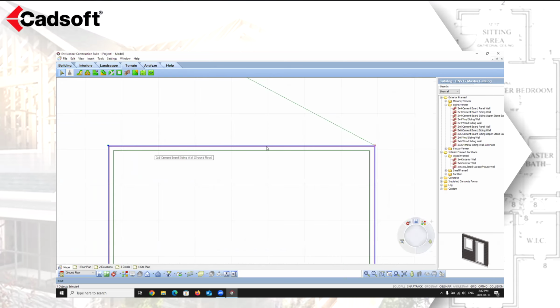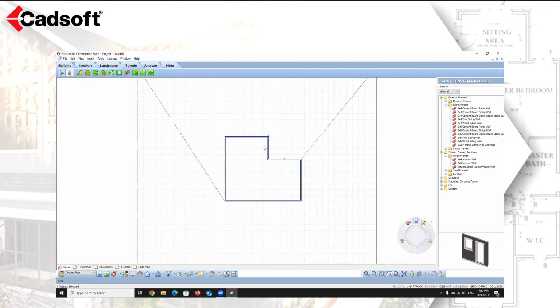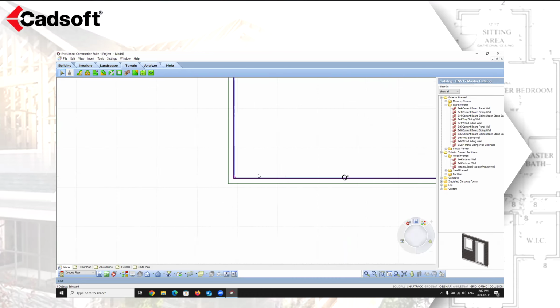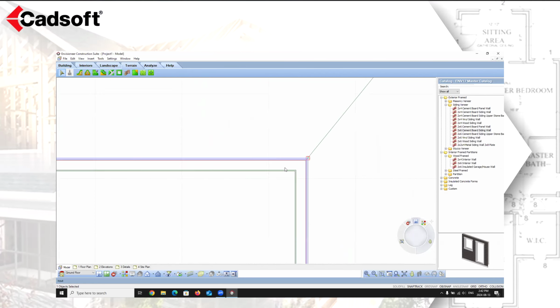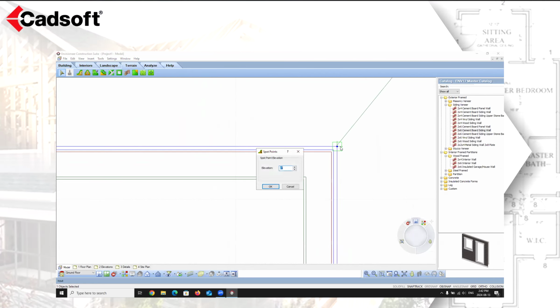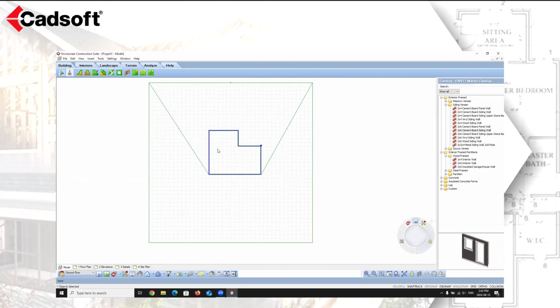I'm going to say okay. And then over here, we're going to go again, minus 2 feet. I know at that back corner, it's dropping down 2 feet. In here, we're going to make this minus 1 foot. We're just going to make it a nice, gentle slope from the front to the back, and we're going to make that minus 1 foot. So that gives me my points from my actual design standpoint.